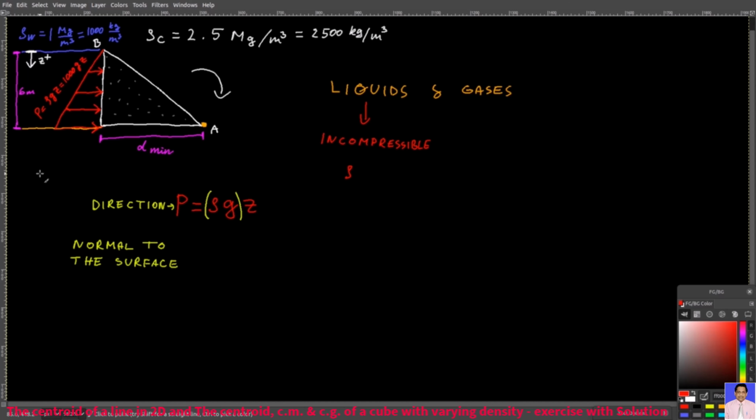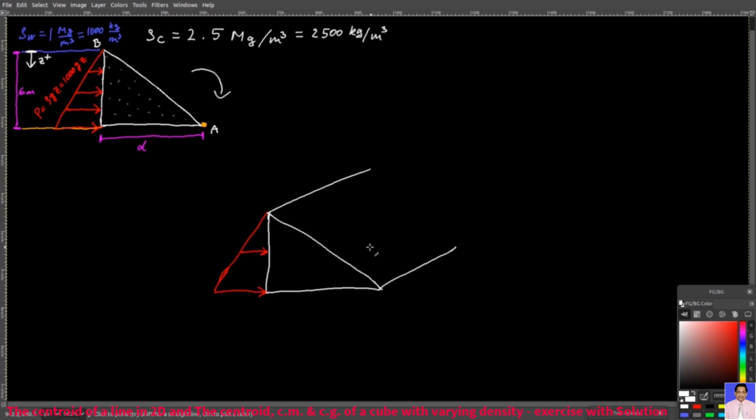So the bigger your depth, the higher your pressure. And just to specify that this pressure distribution is in pascals, so in newtons over meters squared, and not in newtons over meters. Just to clarify that. In other words, it would be more correct to think of the dam in 3D, and the same thing with pressure distribution. When it's in pascals, then this pressure is being applied to this two-dimensional wall of the dam, no matter how wide that dam actually is. You don't need to know that in this exercise though.